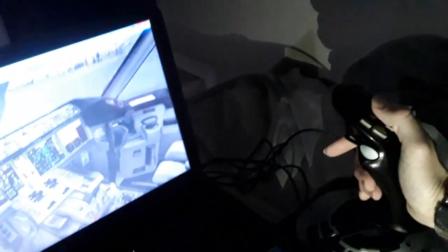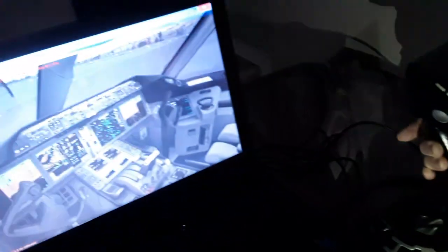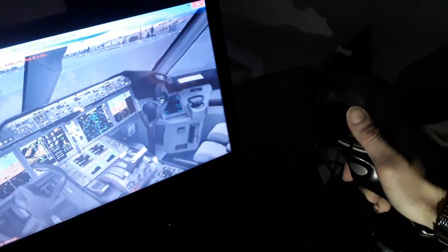Also when we make turns, left and right turns with the Airbus aircraft, left turn is going to be 2.8 G or 67 degrees maximum deflection, or right turn 2.8 G. Also climb 30 degrees or 1.5 G, and descend minus 15 degrees or minus half G. So you can see here we can climb 30 degrees with the Airbus aircraft, or 1.5 G. We can descend minus half G. We can also make turns 67 degrees left and right with the Airbus aircraft, or 2.8 G acceleration at maximum side stick deflection.